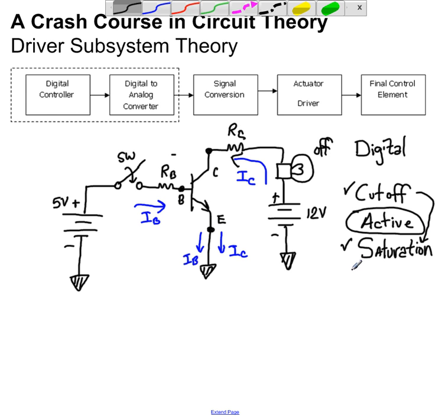If you study the data sheet, you will learn that once the transistor is into the saturation region, the resistance of the transistor from the collector to the emitter becomes very, very small. And the data sheet tells us that the voltage drop between the collector and the emitter can be as low as 0.2 volts in this region. And that is because now you have saturated the transistor.